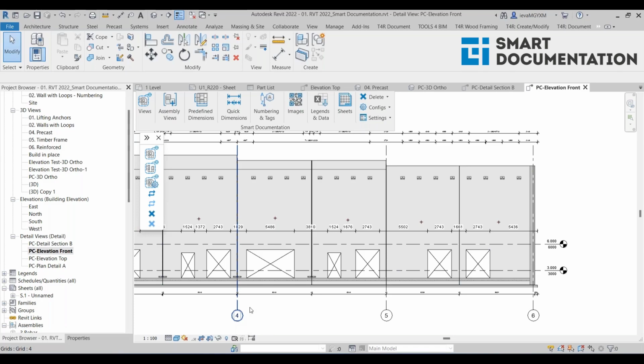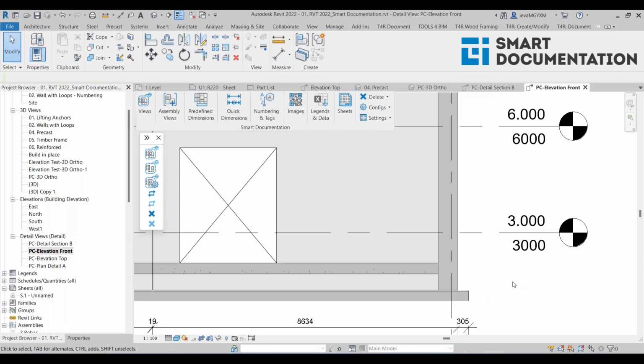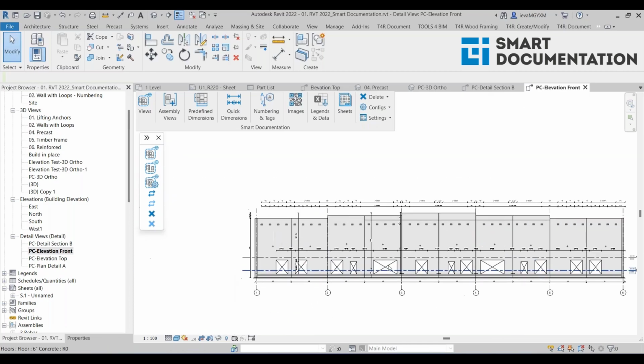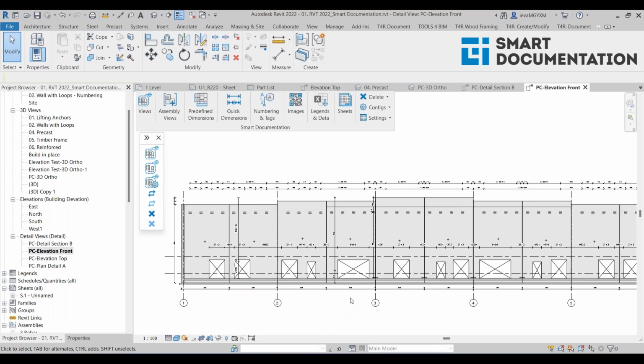We added that feature, but these are actually Revit's grids, and also we can see the levels. So basically, by creating views, we don't have to isolate the element, and we can see the surroundings like grids, levels, and here I have, for example, a foundation wall right here. So yeah, we can see other elements around the elements that we want to create shop drawings for.